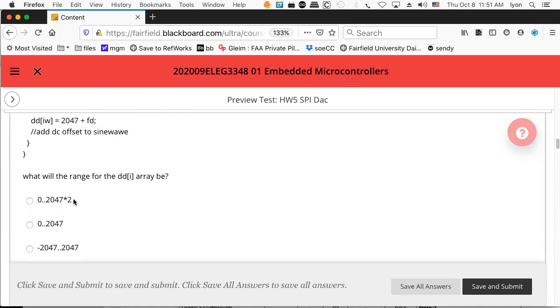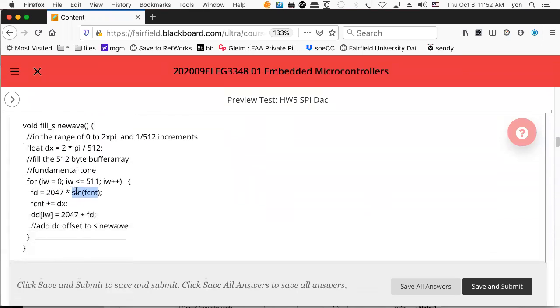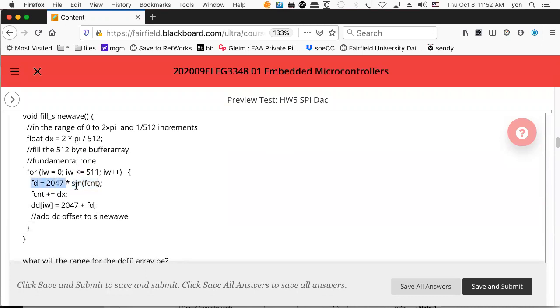I don't know if that sounded confusing. I hope it didn't. But that sort of makes you think about why we're doing what we're doing in here. Because our DAC is an integer device. It doesn't like floating point numbers. It has a fixed point range that goes from 0 to 4095. And so here we have synthesized a wavetable that goes from 0 to 4094.